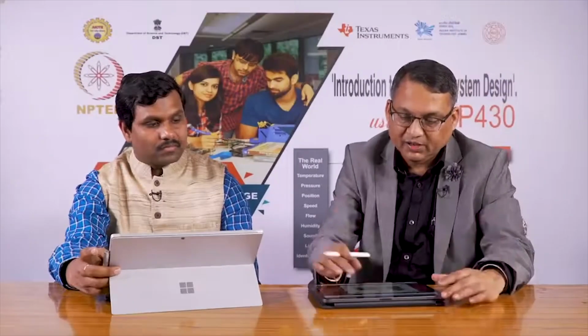Now, this is an example of a custom made PCB which is very good for prototyping. Of course, if somebody says we want to have 10,000 pieces of this circuit, it would be very difficult to do all these manually. What you would do at that point is, with the layout that you created, instead of making the PCB yourself, you can order this PCB to be made by professional PCB fabrication companies, and they would give you a large volume in a small amount of time. You could choose to solder it manually, or even the soldering process can be done in an automatic way.